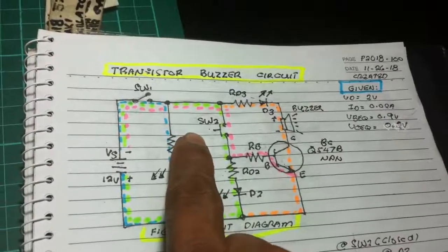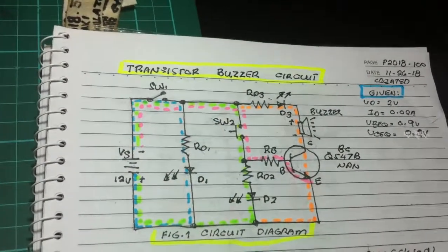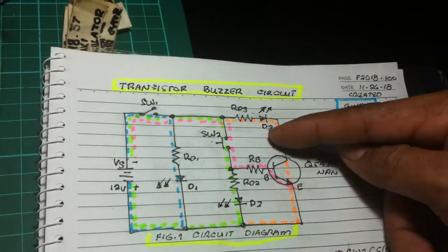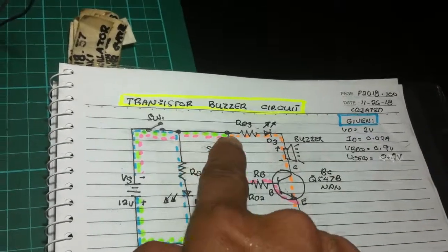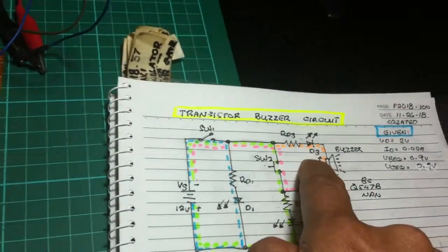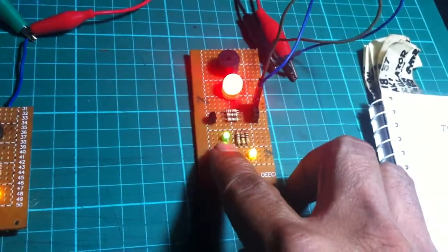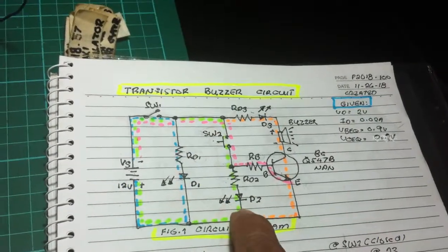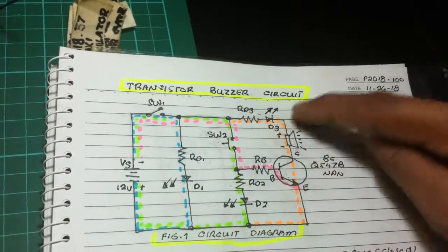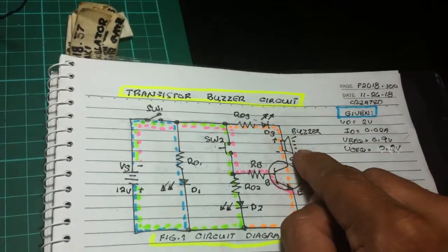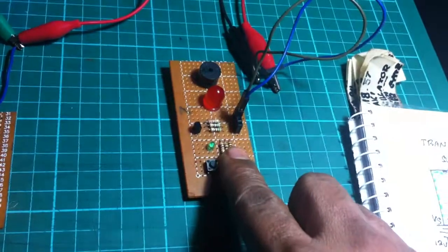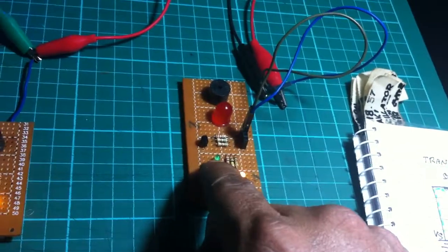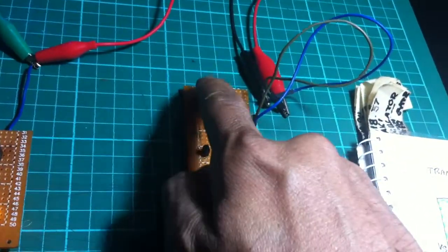So, we are successfully completing the design. Pushing the button, the transistor operates in saturation mode, almost shorted, and we have this output LED turns on. Every time we push the button, the input LED turns on, and also the output LED turns on, and the buzzer is buzzing. Standby LED, input LED, output LED, and the buzzer.